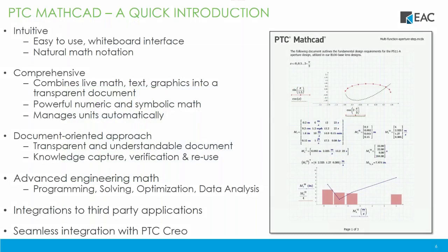On the right-hand side of this slide, we have a picture of a Mathcad document. So just remember that that's a live document. If we make changes to any input variables or design variables, those changes will propagate forward and update all of the dependencies that follow. So the plots will be updated.